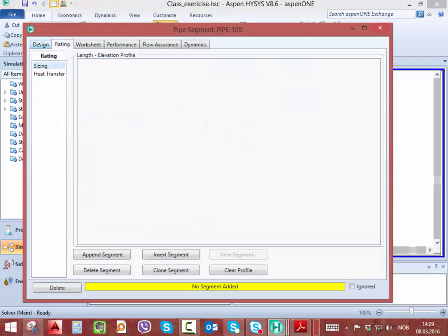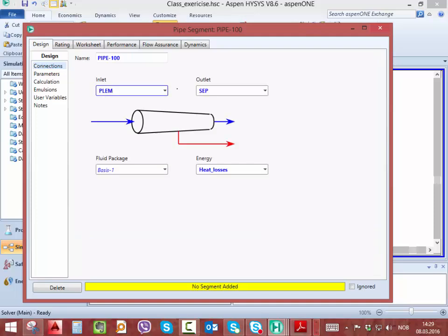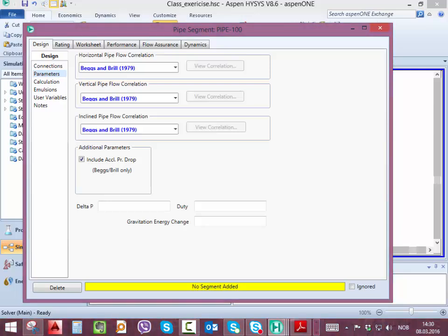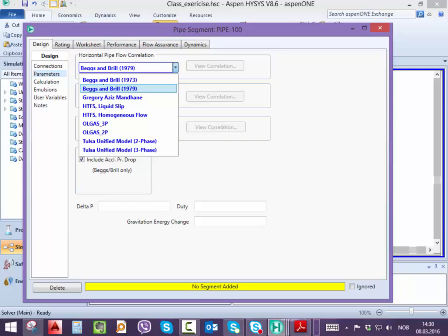I think here is where we left yesterday. Then we made the connection first, and then we checked here. We were a bit curious to see what it has, and you see these are all our experts that I have. And I have actually less confidence in these experts, since Hysys is not really a program to do multi-phase flow calculations. It's a process program, so they depend more or less on everything being single phase. But of course, they want to be attractive also for people doing this kind of analysis, so they give some options.